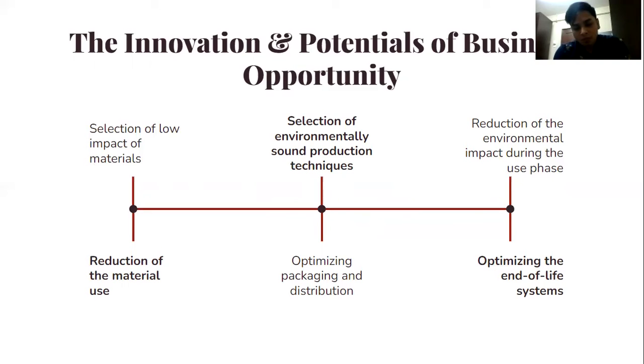For example, raised technical floor is a method of installation of floor tiles that reduces building waste and facilitates waste separation. This floor is a construction system installed on metallic substructures at a certain height above the substrate, allowing the incorporation of a radiant heating system under the flooring.